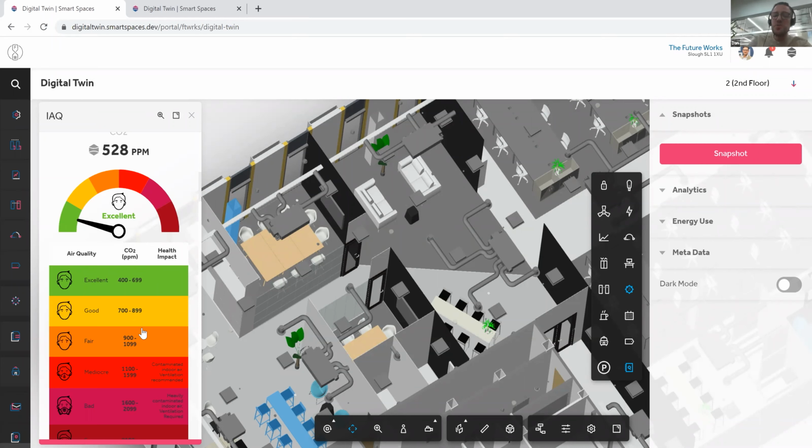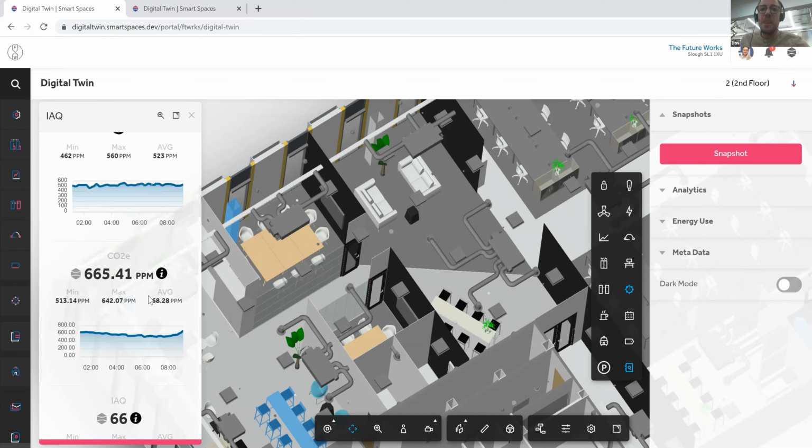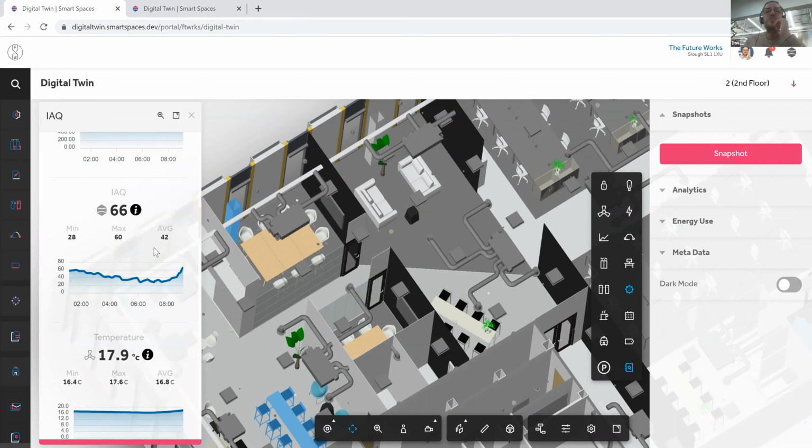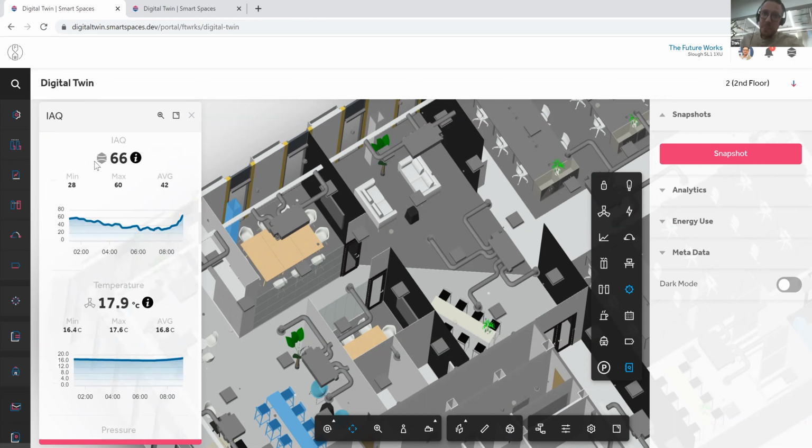We could actually reduce that air handling unit down to, say, maybe 70%, monitor the CO2. And if we keep that baseline, we're not wasting the energy on just changing the air too often unnecessarily. But yeah, so really acceptable range there. We have a synthetic CO2, which is to keep the laser CO2 measurement in check. We have an overall indoor air quality score.